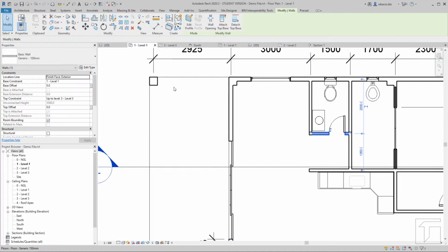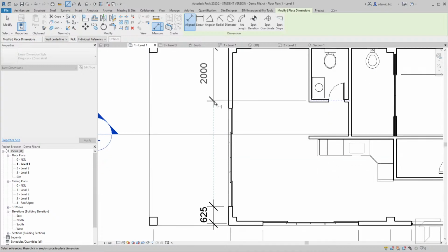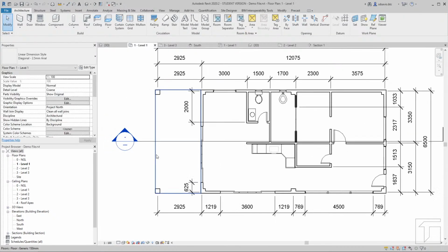So that before we dimension this wall here, it is already correct. The other location of that dimension command is up here on the modify tab, or modify menu. We have this command here. So you click on that, and we select this wall here to this wall here, and then we snap it into place. You notice also if I move it, it automatically looks for that existing dimension below. It snaps into place, and then you click. Then let's hit modify to end the command.